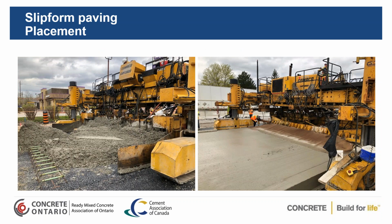Here, now the key thing is that you're going to do your micro texture. Here, there's an initial burlap drag of that. This is the back end of the material. The concrete's extruded out the back. This is the front end. You'll see the concrete has been placed, even on top of the dowels here, where you'll get the machine driving over top of that. And because they're pinned to the subgrade, you won't get that moving your dowel baskets.